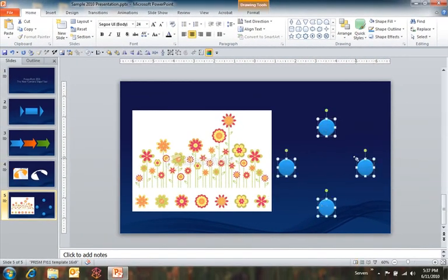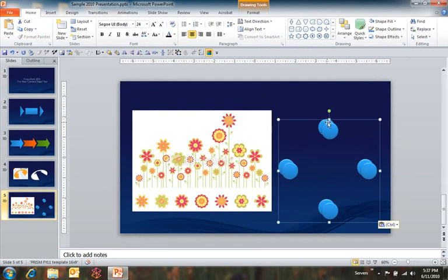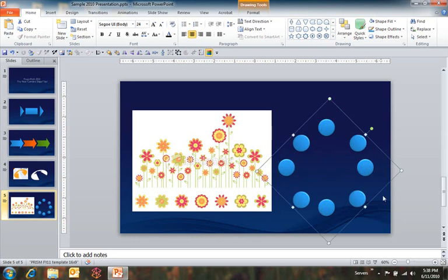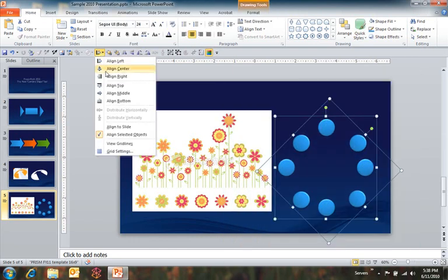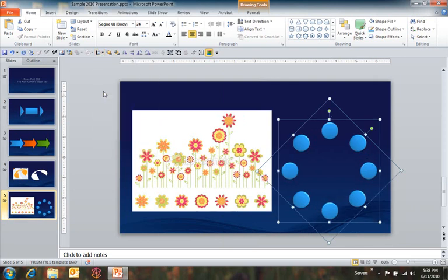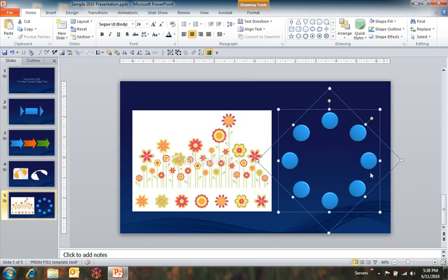And I'll just grab these 4 circles. I'm just going to group them quickly so we can make some quick adjustments. I'm going to copy and paste. Control-C, Control-V is a shortcut. Then hold down Shift. And then if I select both of these, we can just use the Align Center and Align Middle to get them lined up nice and perfect here. And I'm going to group those.